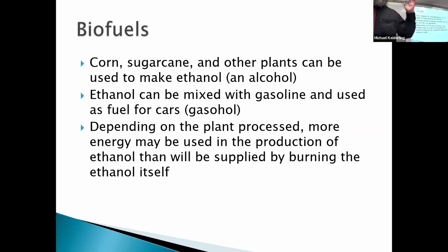It turns out it's not an issue with engines. Ethanol burns in engines just fine. You have to have all your hoses replaced with stuff that will not dissolve in the ethanol. That, it turns out, is the actual problem. The modification to make your car a flex fuel car that can take E85 is basically just replacing all the hoses with hoses that will not be degraded by ethanol.